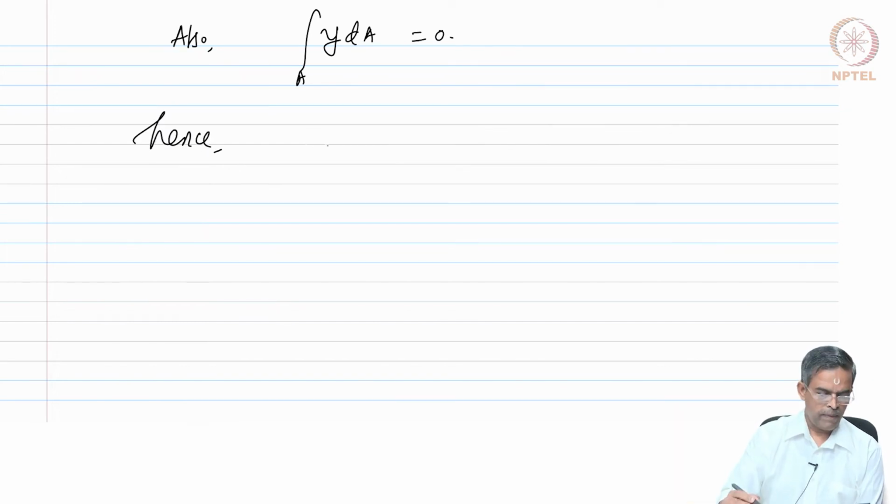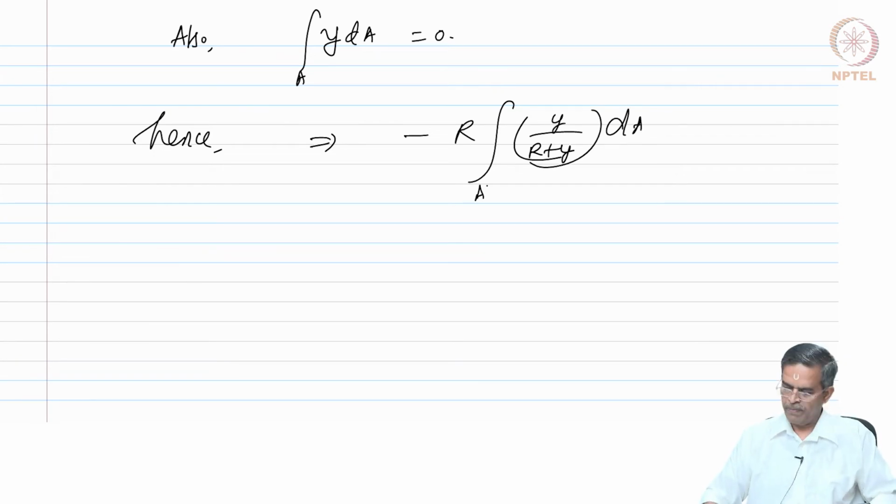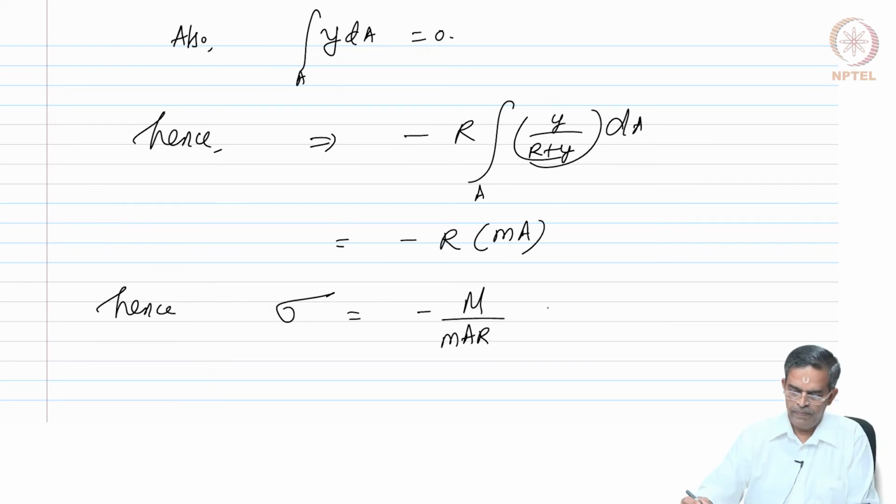Hence, this will now become minus r times of integral y by r plus y of dA for the area A, which will now become minus r times of mA. Hence, the stress equation is now minus Mr by mAr into y by r plus y.